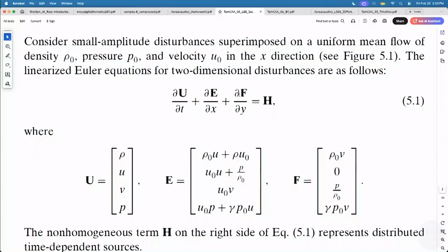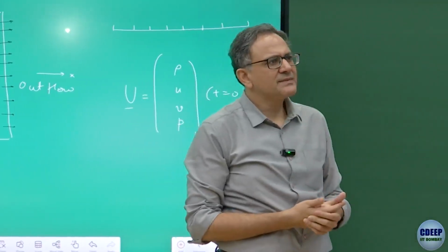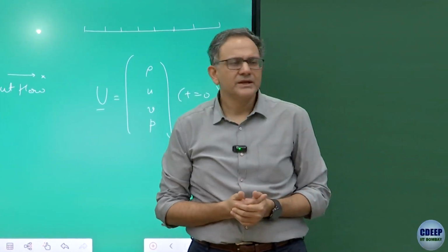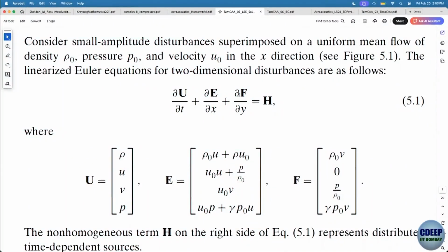Del x, del y, we can get that. So we can get del u del t. In our actual implementation, where does the boundary condition come in? If we don't have any other boundary in the domain, everywhere we know the del x of E and F are known at the current instant. We can find the del x of that, and then that becomes our f of u, which we can then integrate using the optimized scheme to get u at the next instant.